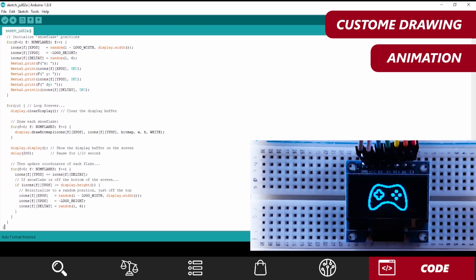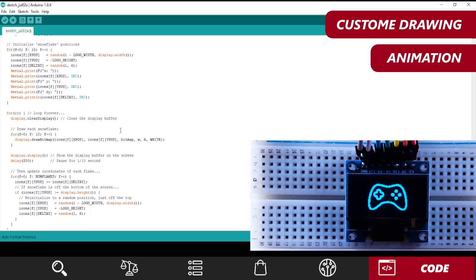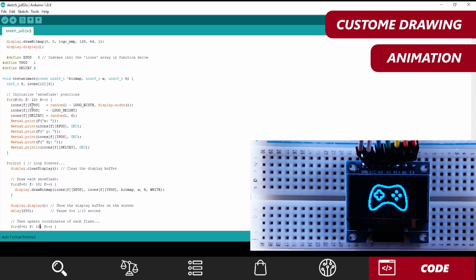First, we need a picture of a Christmas tree and a snowflake. Resize the images as it said in the previous part and convert them to the hex code with the software. Now, after writing the initial code of the display and adding the hex code to the original code using the drawBitmap, we can display the tree image.